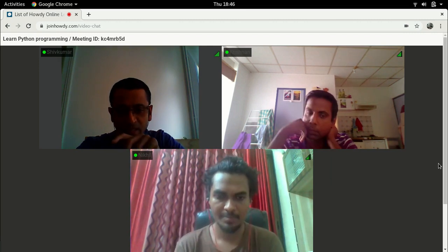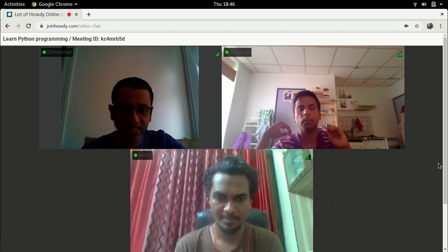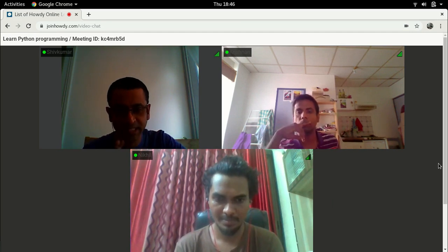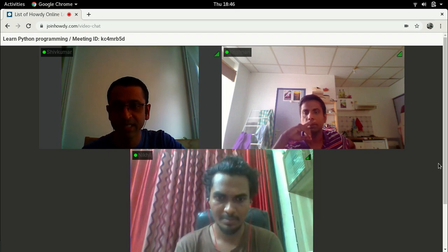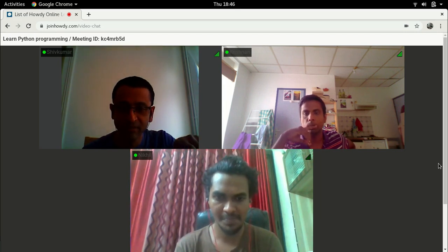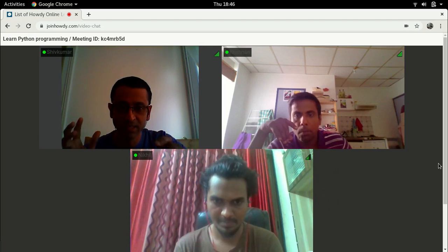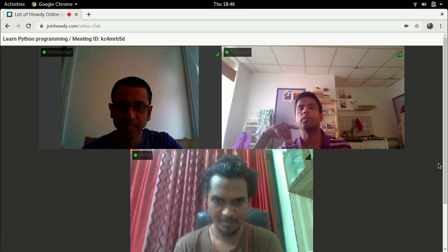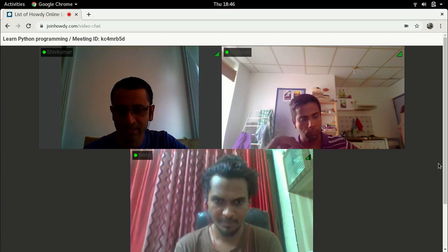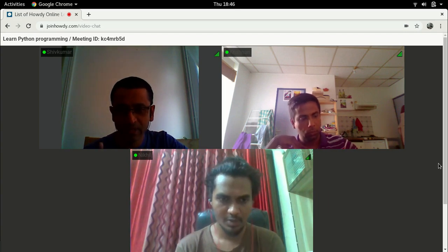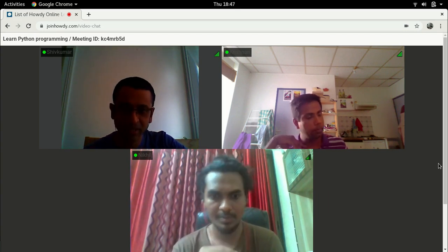It is very important that your matrices be non-singular. At least you have to check for the singularity. Also, you have to check for the structure. For example, if one element is very small compared to the other element, that can be a problem. Say you have e raised to minus 7 and you have 1000. Now there is a problem because there is a huge ratio between your elements. So there are a lot of issues in these kinds of control problems. To be able to get control, you have to define your matrices very well.